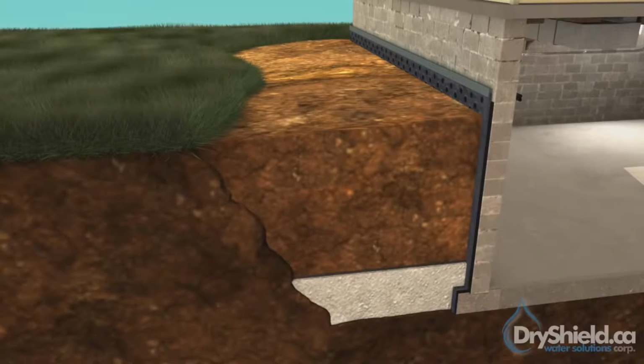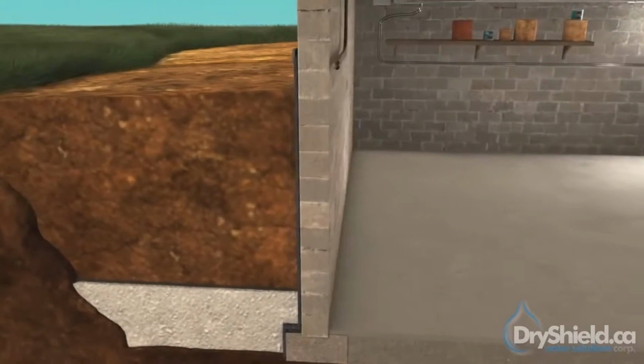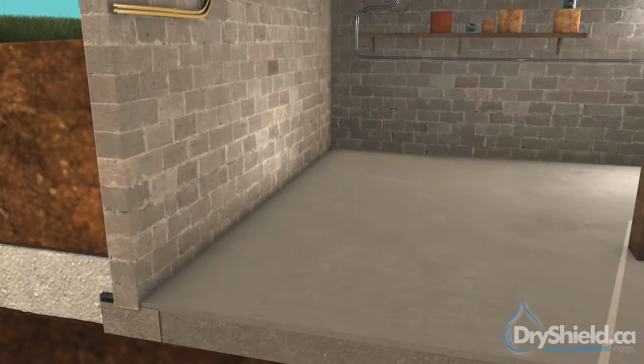Depending on the situation, a more cost-effective approach can be done from the inside. The latest technologies allow for proper internal drainage systems. The key to water seepage is drainage, regardless if done from inside or out. Our internal process involves exposing the foundation to the concrete, and in some cases, the removal of drywall, studs, insulation, and flooring.